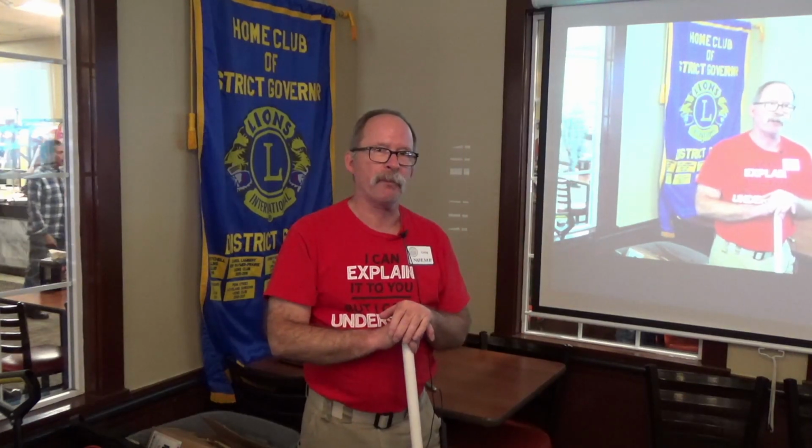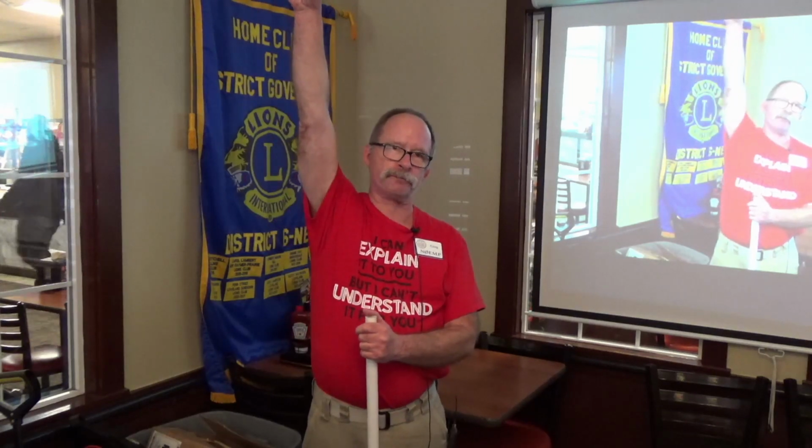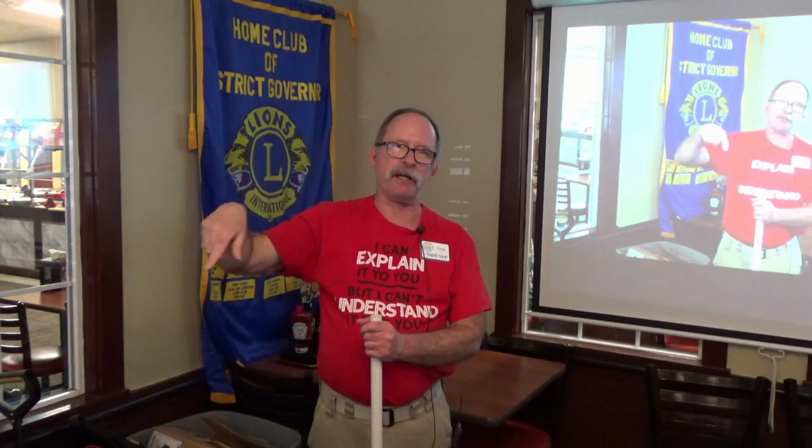You did remind me of something I said. I started off with a manual tuner to really see what's going on. Once I figured out what wire I wanted to use and how I wanted to set it up, with the vehicle as a ground plane and everything else, I went to an ICOM AH4 auto tuner at the feed point, and then a counterpoise wire coming down to my vehicle and tying into it as added counterpoise, and then the horizontal wire going out. And with the auto tuner now, I could change bands without having to mess around retuning.